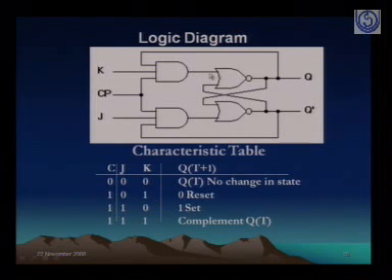So what is the input on this particular side? 1, right? This basically represents your R, so the reset value is 1, whereas J is 1 and Q dash is 0, so the set input is 0. So you get R, the reset value from K, as 1, and S, the set value from J, as 0. So you get 1, 0, which in terms of J and K is 0, 1. This is the situation, so it is going to reset your flip-flop. That means Q has moved from 1 to 0. Isn't it a complement state? Exactly, that's what we want to say.